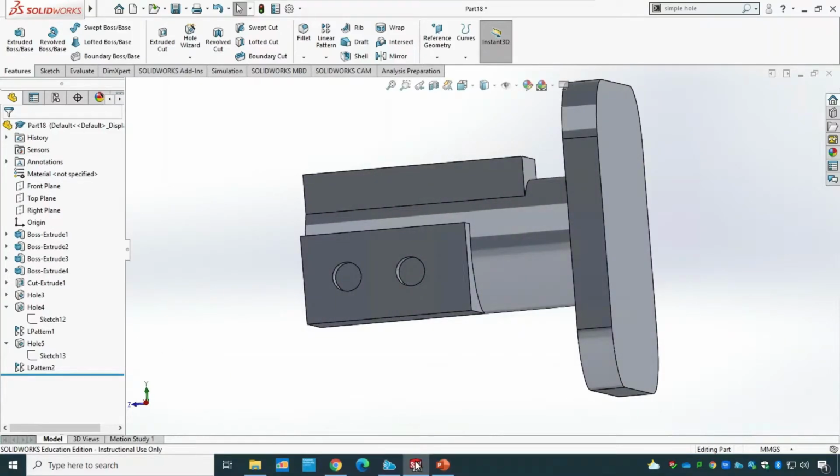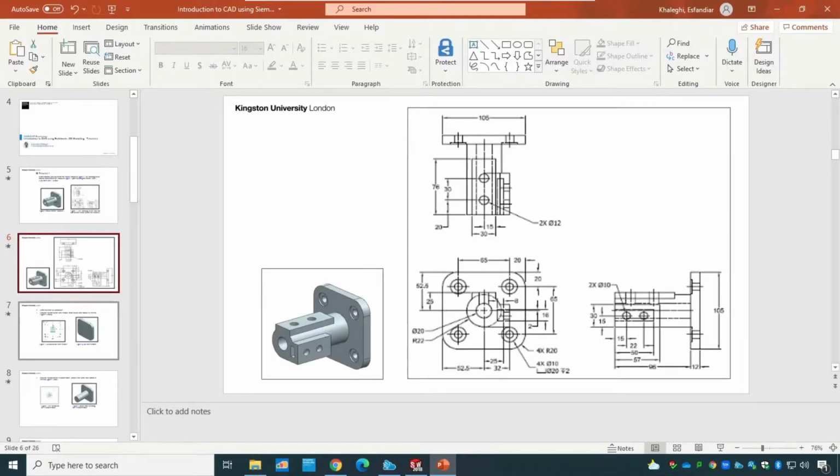And so let me go back to the model. Let's see what we are going to do in here. So now we're going to make the holes on the side. You can see the type of them. That sign shows these are counterbore with diameter of 20, and also the C-bore depth of 2, and you can see they are actually through all in here, and they are exactly in the middle of the fillets that we have, because the radius in here shows the location of them, so it shows exactly the center of the fillets that we have. They are basically the points for the holes.